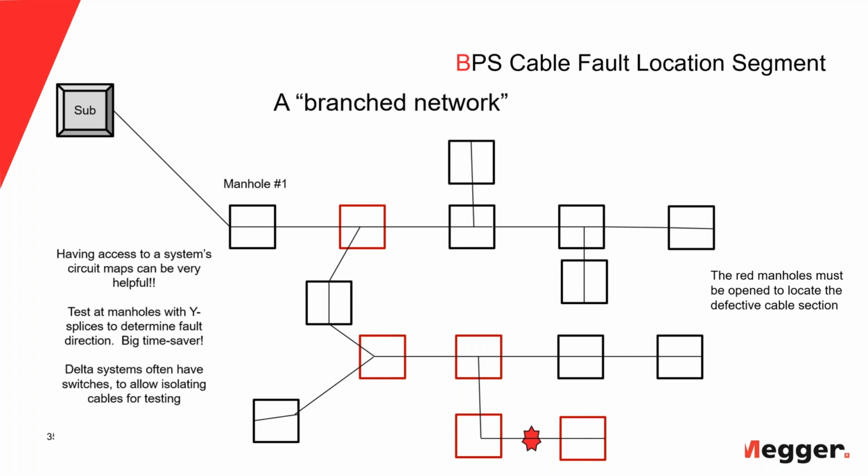It is very, very straightforward, and even if the bonding is not so good, I still get a good signal because I measure the signal right at the cable. I have to put the coil onto the cable, which is on the other side the disadvantage, because I have to open the manhole, and typically I have to pump the manhole out, which can create some other issues. Okay, so that is really the best method in terms of a systematic approach to find the fault.